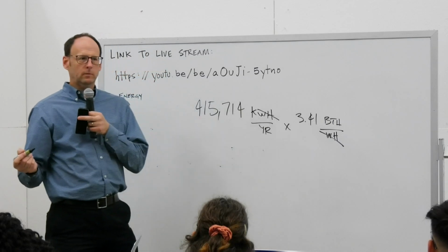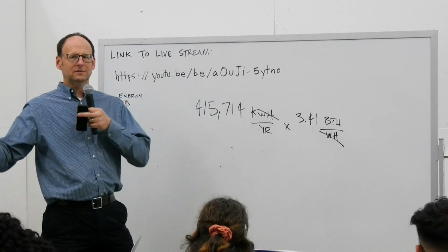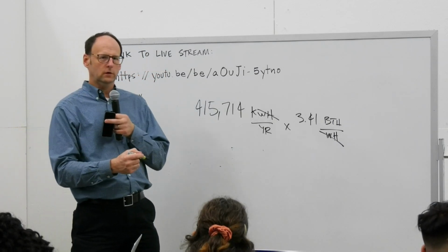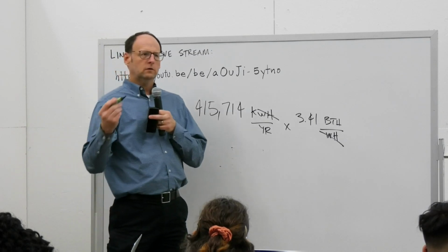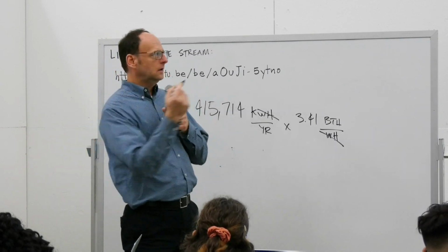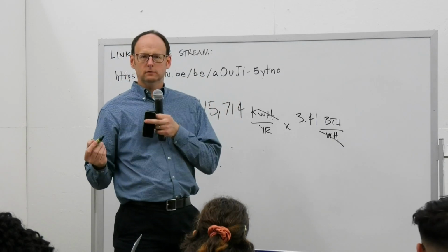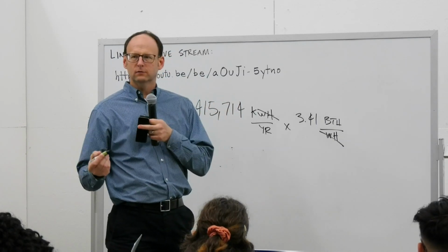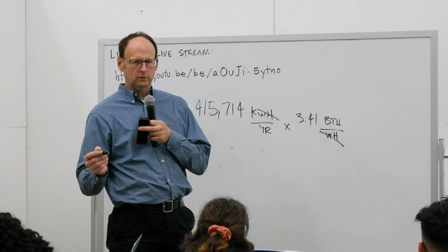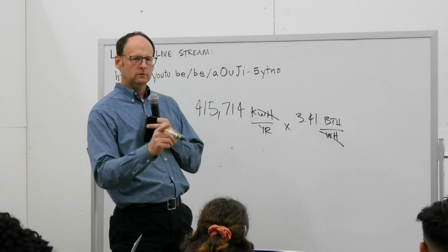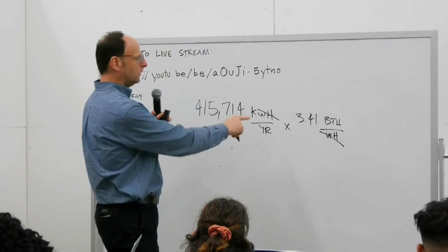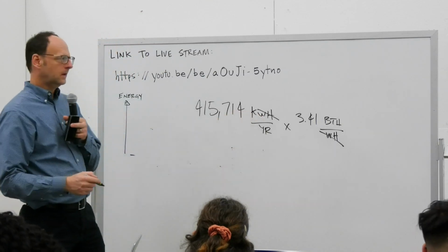That was EUI, if you remember what Bill was talking about, right? He was talking about energy intensity in kBTUs per square foot. So we're going to convert the capacity in kilowatt hours into kBTUs because that's how we understood energy intensity for our buildings. It's a simple conversion. So everybody do this with the calculation you got from PV Watts. Just multiply by 3.41, okay?